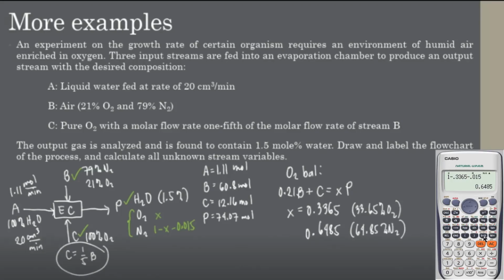And with that, we have also solved for the composition of stream P. And that's the nature of material balances. You just have to exploit every possible material balance you can form. That is, first, the overall material balance, and then after that, you can perform individual component balances. After this lesson, you will be given more examples detailing the proper material balance solution for different types of process units. Certain process units have particular modes of solution, and it's important that we discuss all of them.